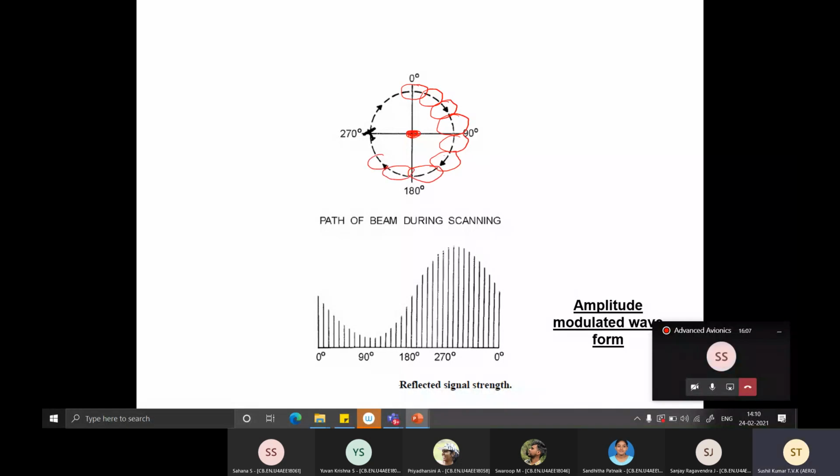So what's going to happen is, whenever this particular antenna beam crosses the target, and this happens to be 270 degrees, the signal output is going to be maximum. Okay, and then you keep doing this again like this. Again, zero is somewhere you reached here, and 90 degrees is exactly opposite, so you get a V minimum.